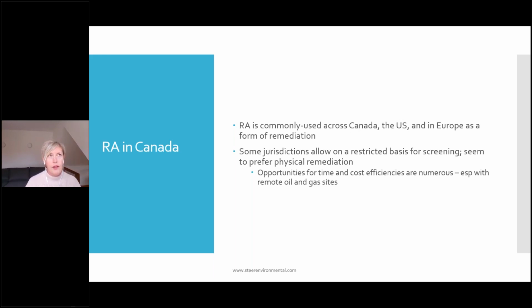CFC. Now, there are prerequisites to even attempting risk assessment when you're looking for closure like that. One is that all contamination needs to be delineated. The site investigators need to demonstrate that all of the contamination is stable or decreasing in concentration and extent. And there are specific requirements around the type of monitoring and the amount of monitoring that is required before you can say, yes, we can provide assertion that it's stable or decreasing.